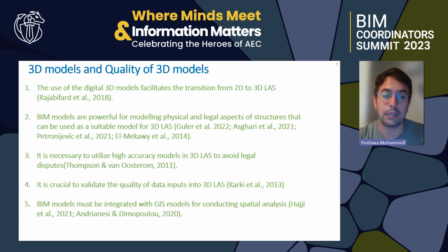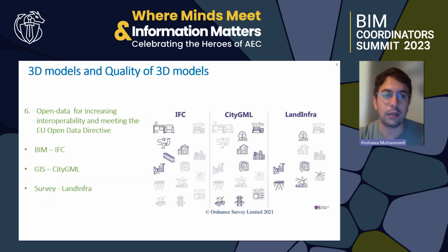And BIM models must be integrated with GIS models for conducting spatial analysis on the 3D LAS. And finally, it's very important to use open data for increasing interoperability between different sectors, and also to meet the EU or international open data requirements. So IFC is Industry Foundation Classes. IFC is one of the most popular open data in BIM that can be used for sharing the BIM data within or between different stakeholders.